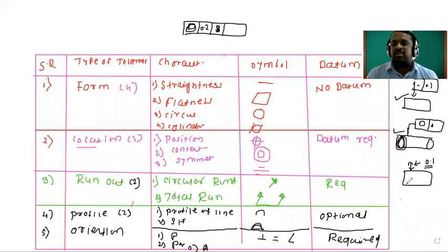And what is the symbol for that? We have to develop the symbol. Every time we can write here that the tolerance on the flatness is required within 0.02. No, so for this purpose we have developed these symbols. We just have to give the symbol and give the tolerance, so that automatically we can easily understand. For this component we have to follow this point only during manufacturing. It means the surface flatness, straightness, and circularity of that component should be within this tolerance only.